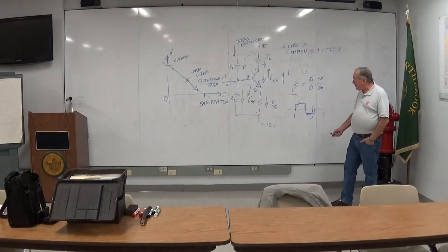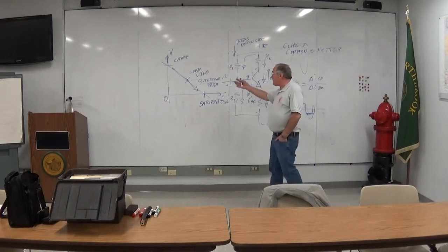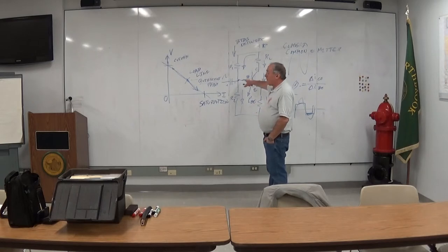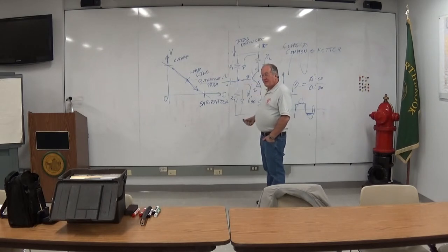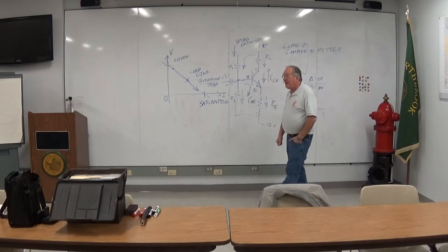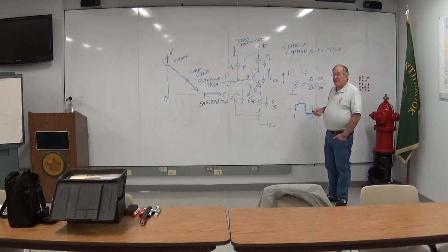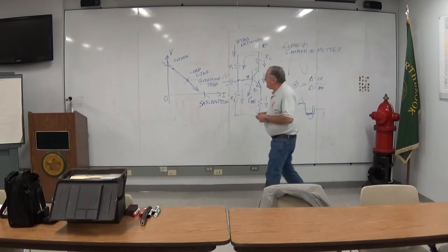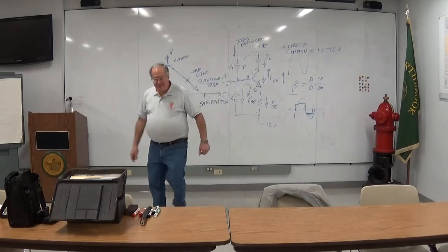If you just want to use it as a switch, well, that's not the way you configure it. You would basically probably not have this resistor here. This thing would be clamped off except when a signal shows up to make it turn on. And transistors are used as switches very often. In computers, all the time. That's basically what they do. We'll get to that subject.